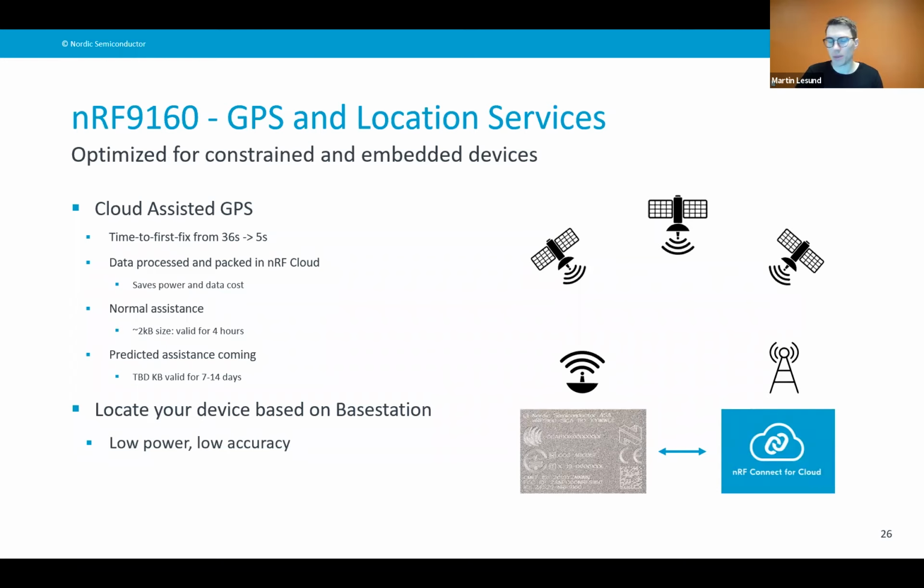And we also have some GPS improvements with regards to assisted GPS. Usually we get almanac and ephemeris data from the satellites. So the GPS receiver is on, we download the almanac and ephemeris data at very low throughput. This can take a long time. The GPS is on, the GPS uses a lot of current, and then you can start to search for all the satellites and get a GPS fix.